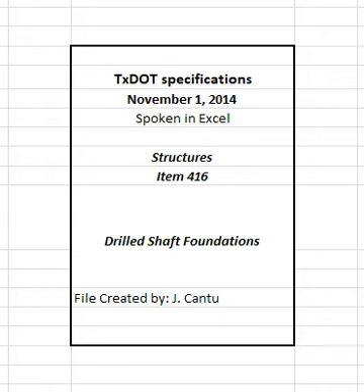Complete the embankment at bridge ends before installing drilled shafts that pass through the fill. Refer to Item 423, Retaining Walls, for provisions for drilled shafts passing through the structural volume of retaining walls.